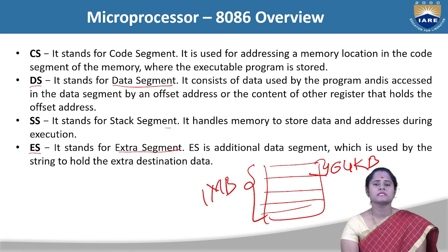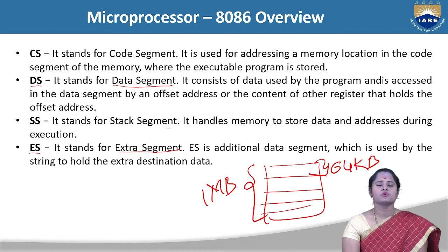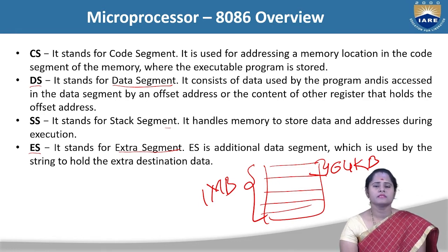Why is my memory divided? What is the use of memory segmentation? Memory segmentation is dividing my memory into several blocks, like a code segment, a data segment, a stack segment, and an extra segment, each of 64 KB. So what is the use? Let me take one example.